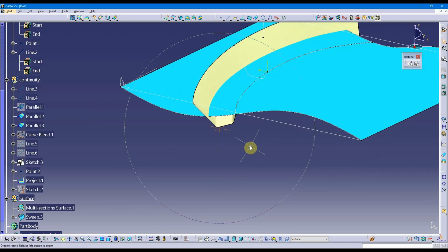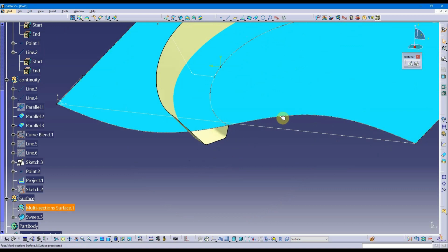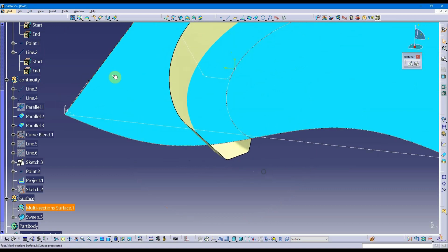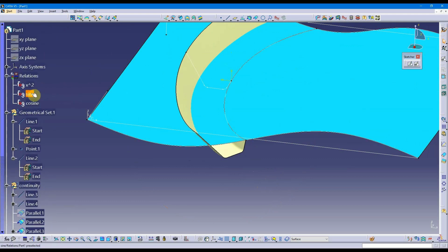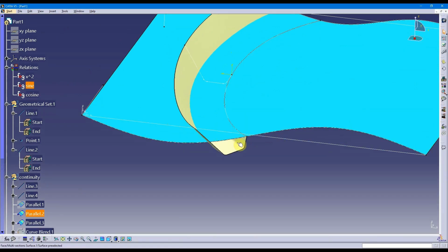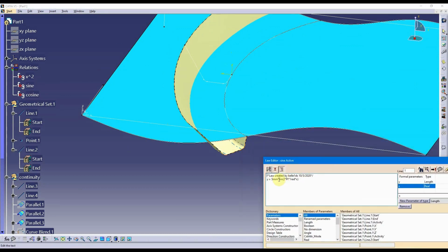So for demo, let me just show you what happens here. So this is one of the ends, and I've got this sine curve created with a law, and I did that intentionally so I can go into my sine law, and I've got an amplitude here of this law. Let's see what this looks like. So I've got it set at 5 millimeters. So let me adjust this out to 20. So the amplitude right now from my original curve up to the peak was 5. Now I'm adjusting this so that amplitude will be 20, so it'll be 4 times more.